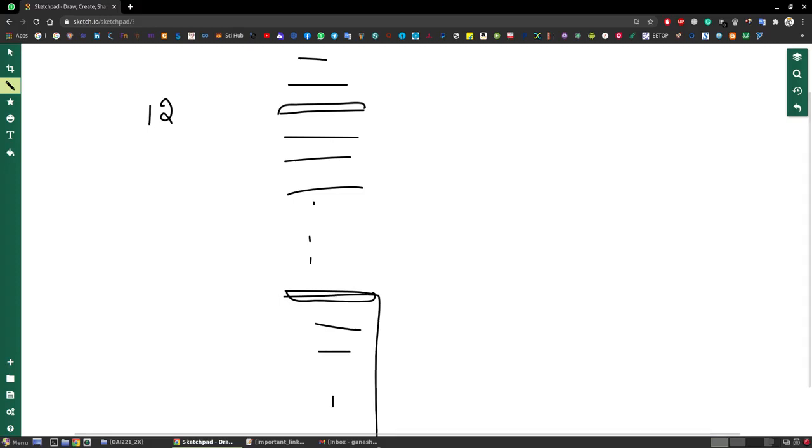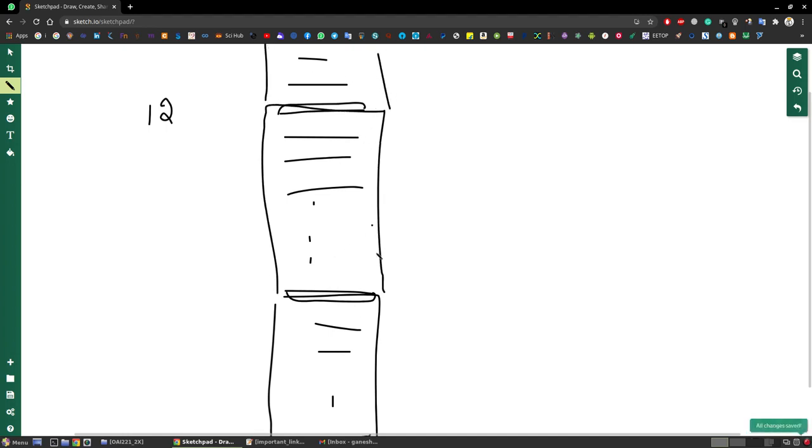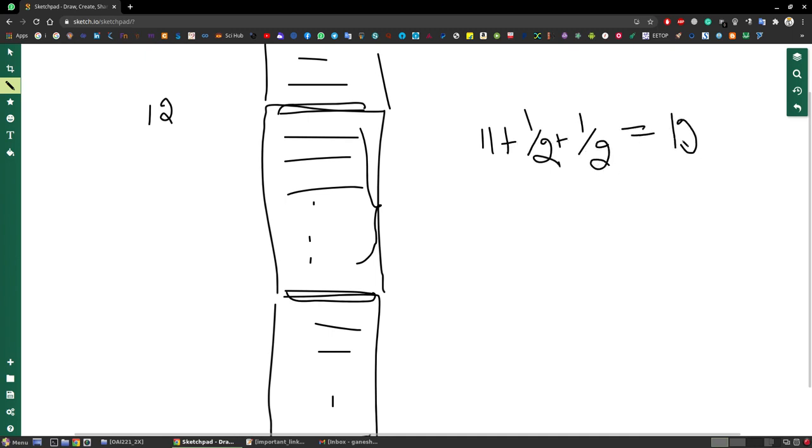So this is one standard cell, and this will be your one standard cell, and this will be one more. So the VDD and VSS will be shared. So the contribution from VDD and VSS is only half each. So finally there will be 11 middle tracks, okay, plus half of VDD plus half of VSS. So totally a 12 track library. So we need to draw 11 middle tracks and half of this VDD and VSS.